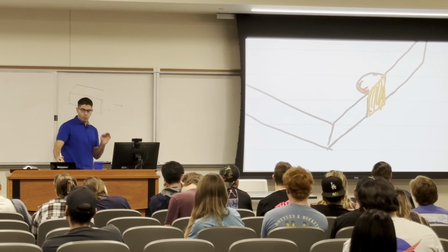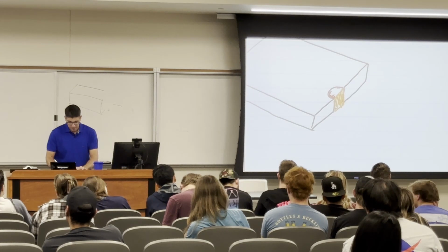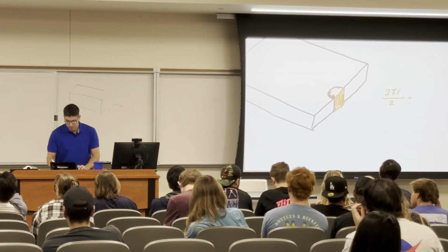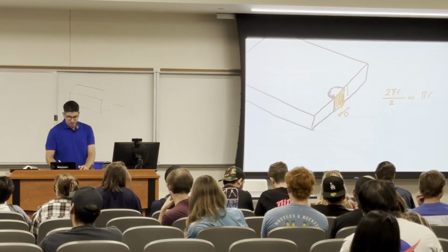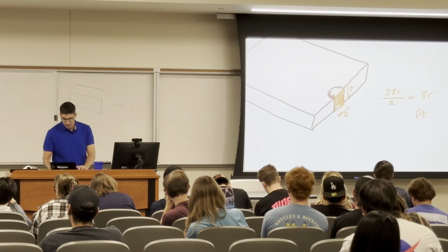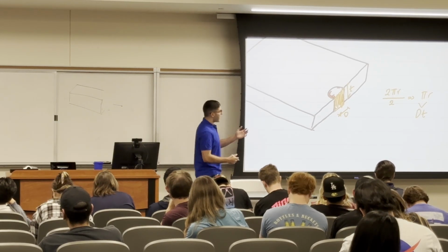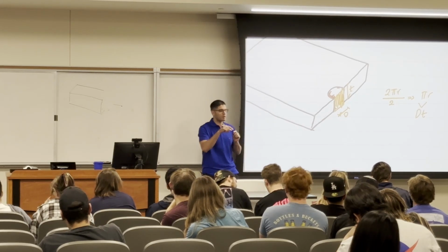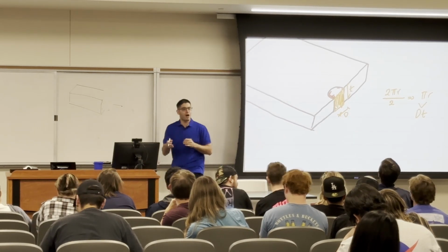I don't want to take the circumference because, if I compare, the circle is 2 pi r, which is the whole circumference, and if I divide it by 2 for the half circumference, I will have pi r. But if I take the rectangle, which is the diameter times the thickness, I will have d times t. And d times t actually is smaller than pi times r. So now I have a very close approximation of the non-uniform stresses, and actually we're not underestimating anything. We are getting a smaller area than half the circumference.